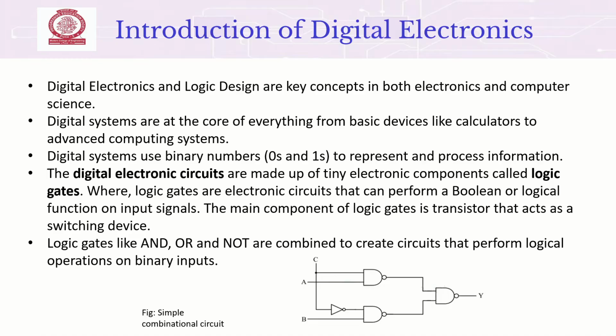This also reduces the chance of error in design and construction of the digital circuit. To reduce the logic redundancy, there are various techniques in digital electronics such as Boolean algebra, K-map, and the Quine-McCluskey method. These all reduce the logic redundancy, which makes the circuit simpler and also easier for us to evaluate.